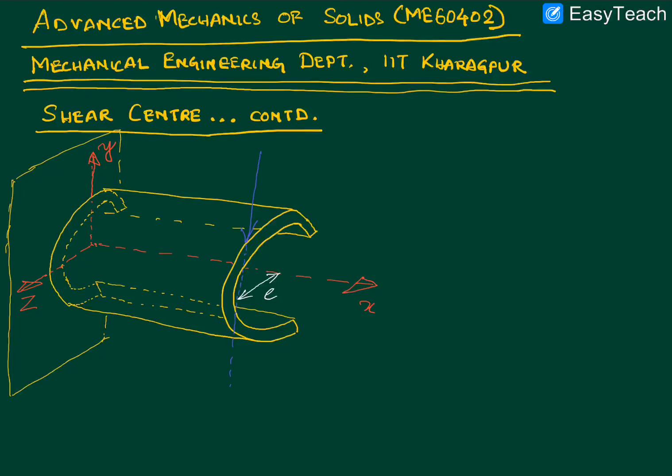Now one may think immediately that we are only considering a transverse force which is parallel to the y-axis, but please note that there is no restriction about the choice of this y-axis and the z-axis, other than the fact that for the requirements of a derivation they have to pass through the centroid.